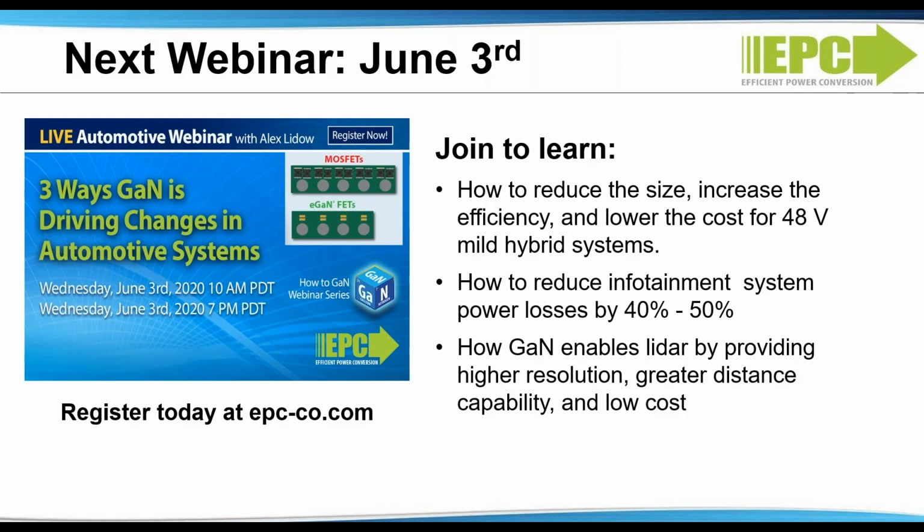What is the package inductance in the EPC2045? 0. There's no package, so we have no package inductance, and the internal inductance in the product is about 2 or 3 picohenries. It's virtually 0. So all of the inductance is the inductance that the designer adds in the PC board and other components.